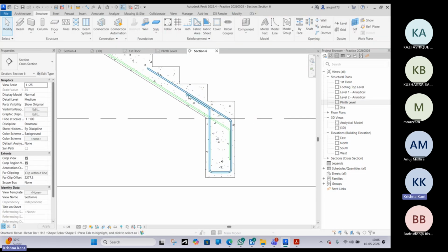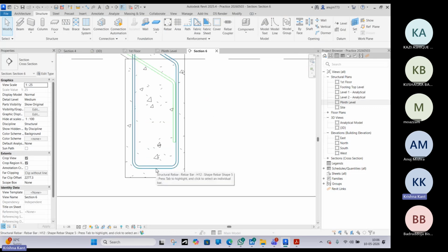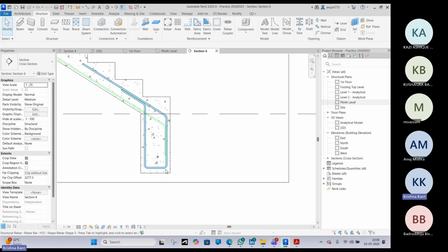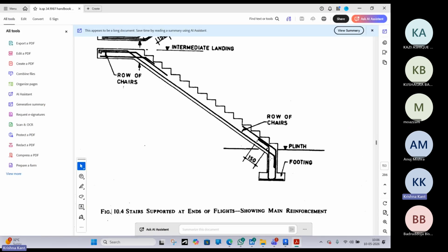But sometimes in structural design, the engineers will give a different design detail. Suppose they just turn this and bring it up to this bottom only. Okay, only one top is fine. But right now, as per SP34, we have to bring it in this direction and then we can bring it up. Okay, this is how we provide one rebar for the bottom.